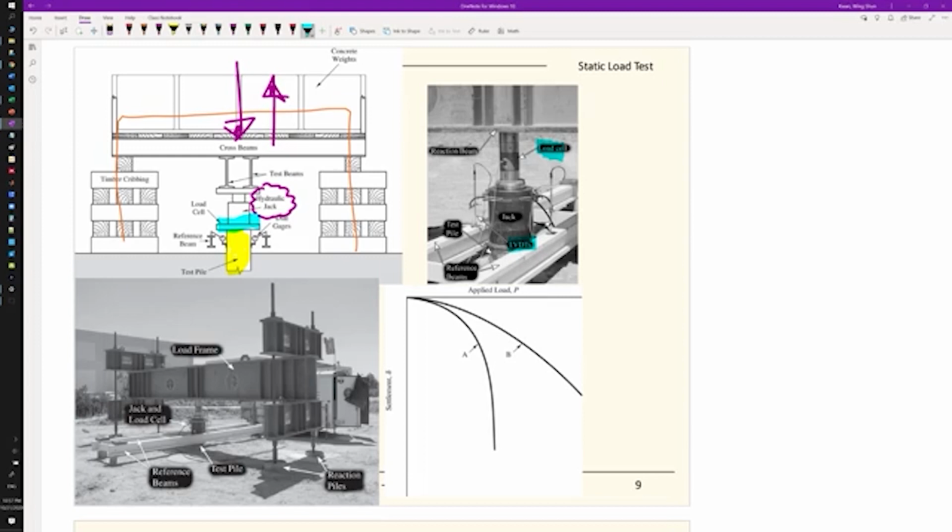So you get the interaction between the pile and the soil, and you also realize that those displacement sensors are installed on reference beams, because when the whole thing is in action, the pile is moving, and you need to have the zero reference point to know the displacements. Those reference beams are stable in the ground, anchored far enough from the loading pile to make sure the beam is not moving, but the pile is moving. So the relative difference in location is the displacement that you want to measure, which gives you the response of the pile when you're mobilizing the soil.